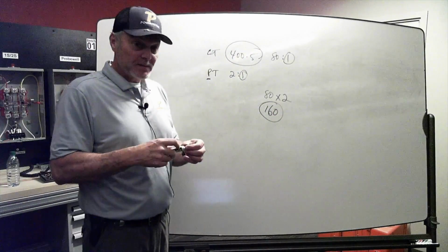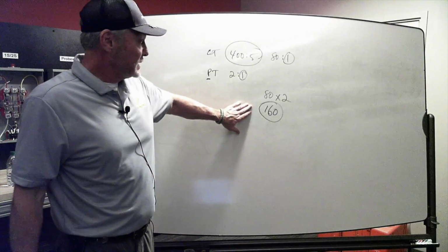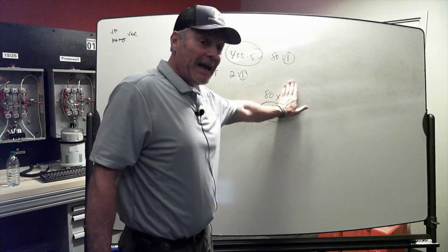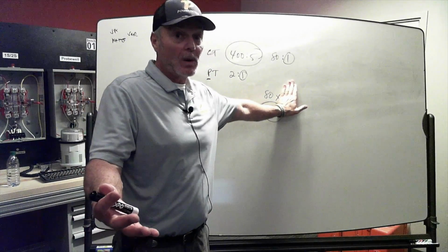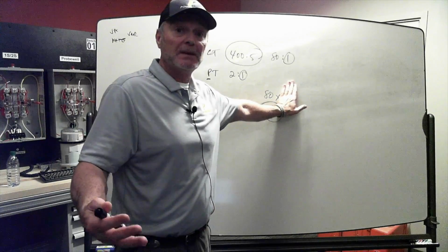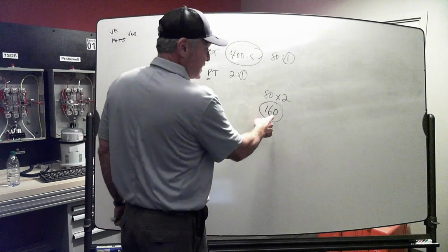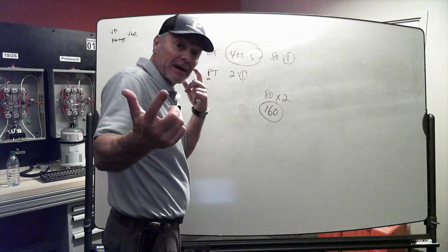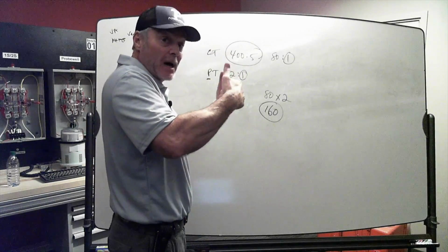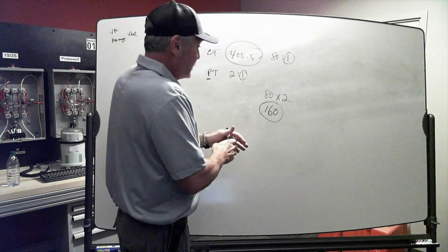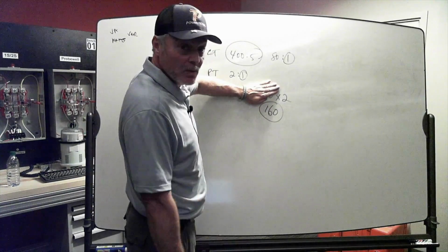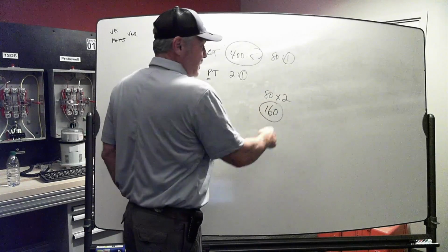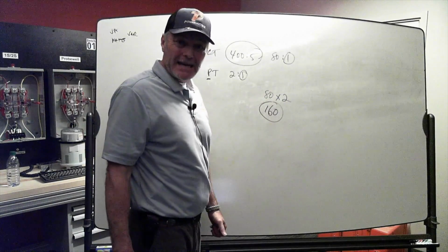Now, here's where we have the problems. If it's supposed to be 160 and somehow this gets left off and you're only multiplying it by 2, or only multiplying it by 80 because of a mistake out there, and we've said that before. That's one of the major mistakes out there, billing multipliers. What happens then, and think about the bill. Instead of the amounts measured going up 160 to get to the bill, you only do it by either 80 or 2. You're losing your shorts, right? Because now, instead of multiplying by 160, I multiply by 2, I'm missing out by a factor of 80.